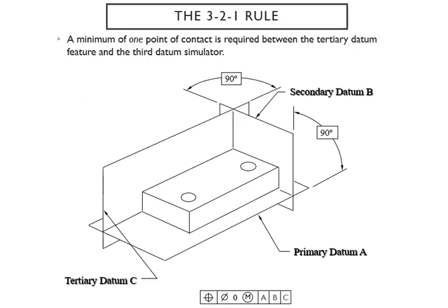Okay, and then we come to, of course, the tertiary. So this is what I'm talking about. This is 1 point, that's 2 points, and then the surface is the third point for A. The surface is the first point, I should say the point on the surface, and then the one that is connected to the edge, or along that line, is the second point. And for the tertiary, you can just count the point on the surface because you have already counted this with A and also with the secondary, so you don't have to repeat again.